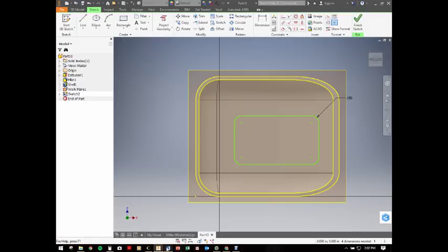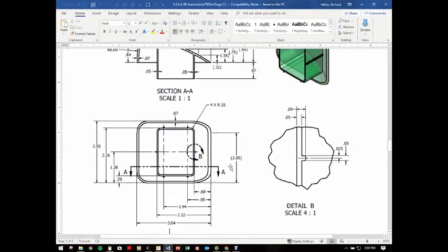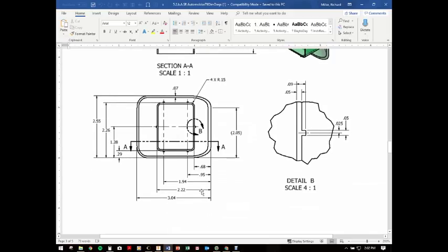And then this system here uses a type of dimensioning called datum dimensioning. Datum dimensioning, as opposed to chain dimensioning, takes all of your distances from a known point called the datum point. So everything comes from the leading edge here of this windscreen going to the left. Same thing, it goes from the bottom of the windscreen here going up. A chain dimension would have gone from here to the edge and then from here to here, and it would have been a series of numbers in there. This is a lot neater. The problem with this is that I have to use my calculator to figure out the thicknesses of certain things, and you'll see this in just a second.